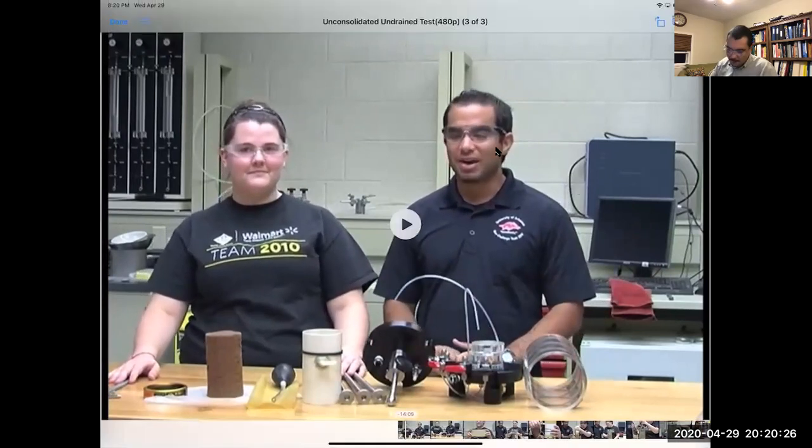So let me point out, this is your soil sample, and at the start of the test, you would measure the length of this sample and the diameter of this sample. You would take 3 measurements and average them out, and same with length. You would measure length from here, length from this side, and length from the back. In measuring the dimensions, you can calculate the strain change before and after the test.